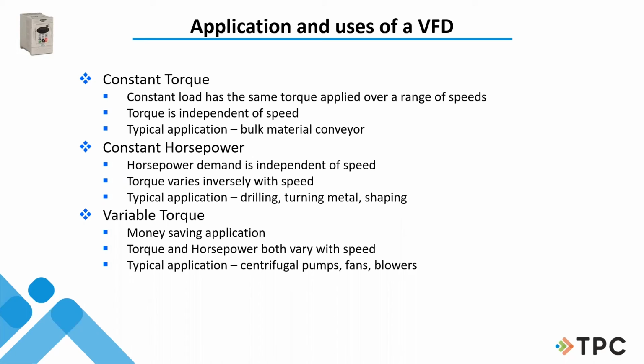So know what those things need to be. And again, you have to set the parameters to variable torque instead of constant torque. It's going to be in one of the parameters in the drive. And if you don't set it, then you're not going to save the money. A lot of people get things installed by contractors, and I don't know who tells them how to set it up, but they don't set it up for variable torque. So you're not saving anything. You just got a drive on a pump that's not saving you any money at all. Might be saving you a little bit on maintenance.